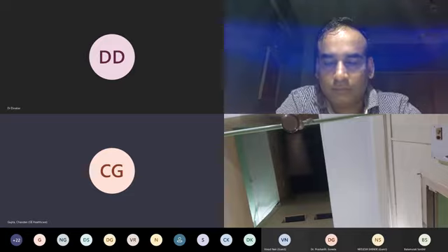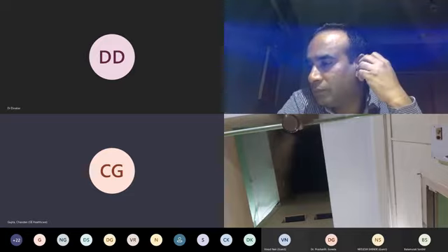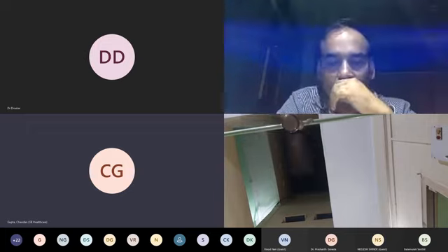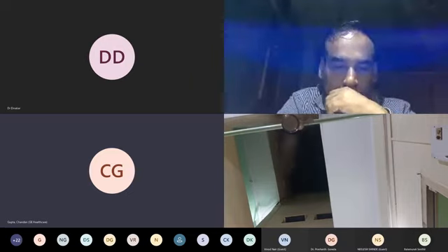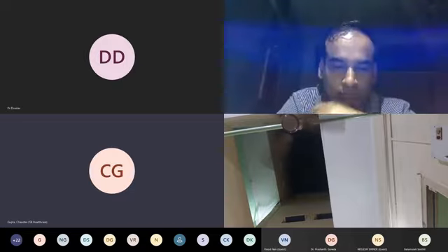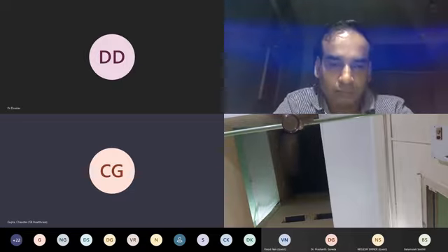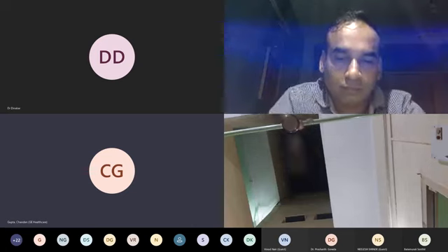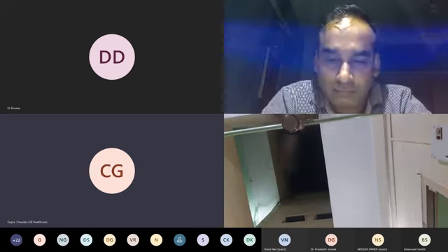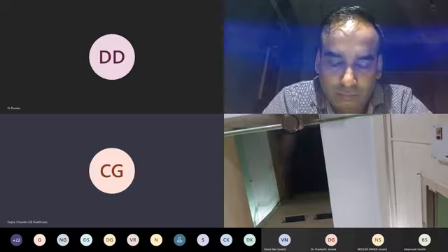There is moisture, the paper is there, and then the hot air goes over that, it collects that moisture and it mixes with the air and comes. That's the way we give the humidity in the ventilator. Now most of the value segment incubators use a similar principle where humidity is given in a moisture form.